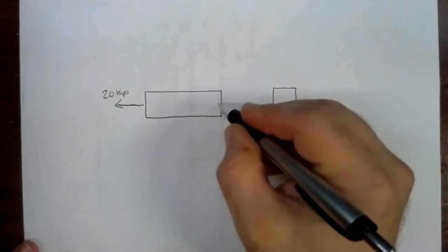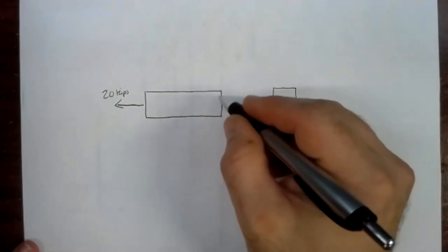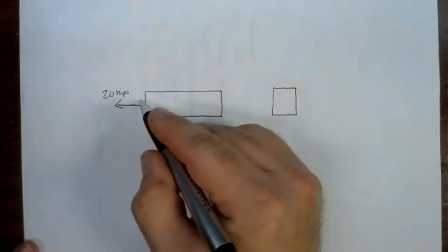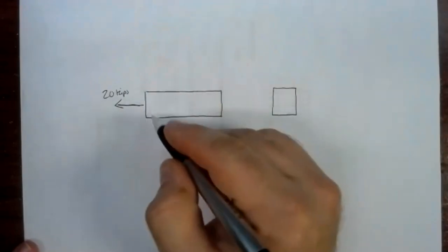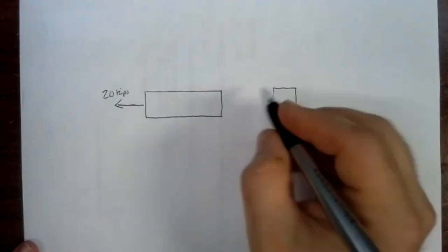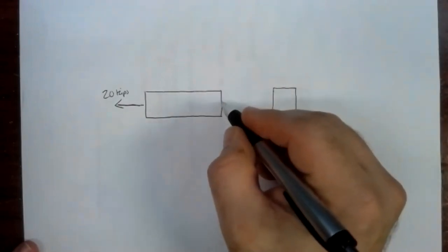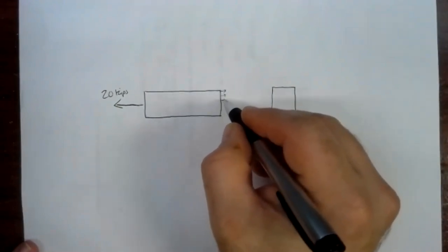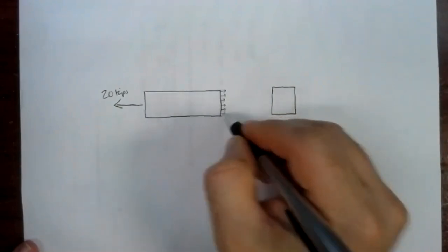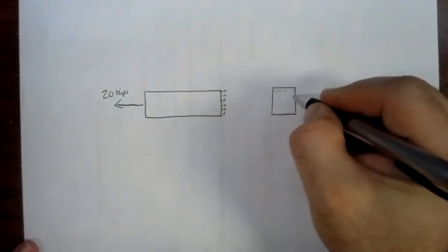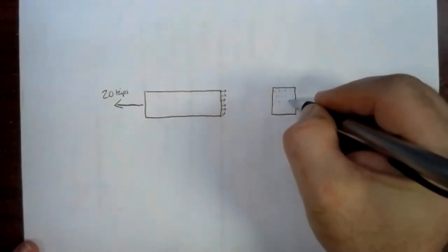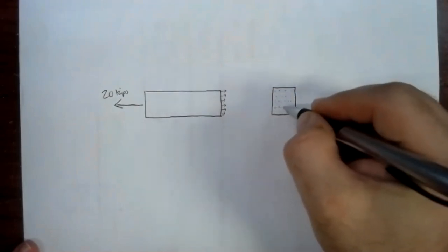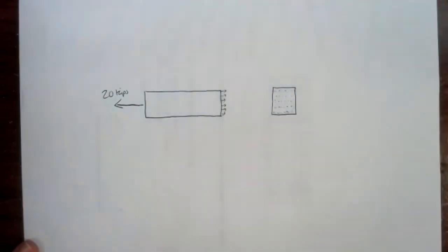The force that we need to apply on this end that we've cut has to add up to 20 kips. Otherwise, this thing won't be in equilibrium. But the force isn't applied at a single point. That force is spread out over this area. So it's drawn in the notes looking something like that. What it really is, we'd see little dots. If you imagine these dots are the heads of the arrows that we're seeing here, every square inch of area has some amount of force on it.